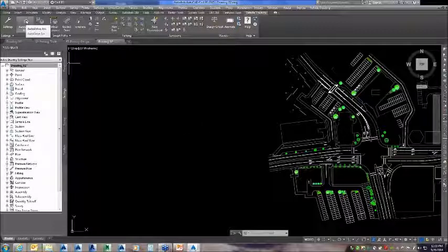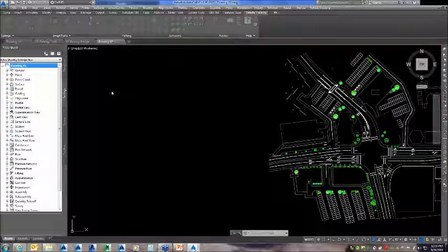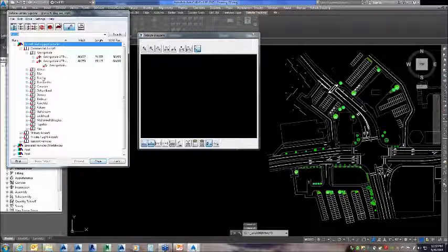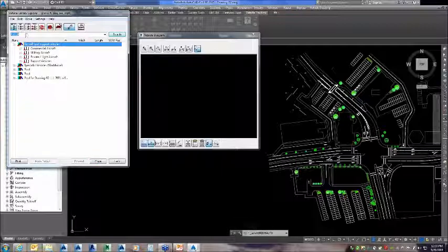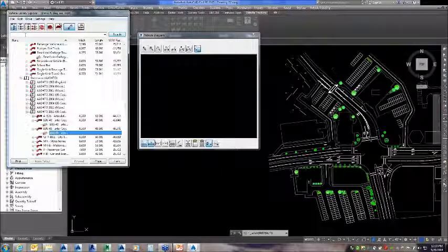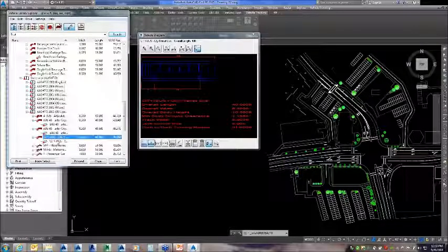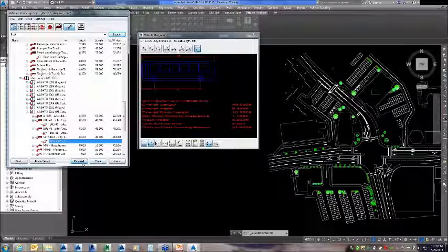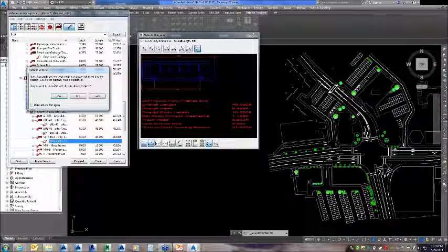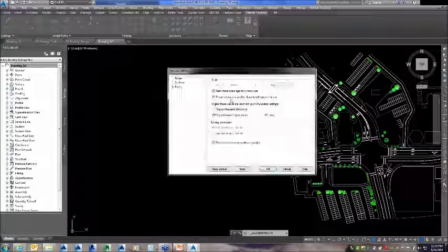So if I pick AutoDrive, just right here, it's going to bring up this dialog box again, and I'm just going to go down and pick a specific vehicle. So if I go to search, I'm going to go down and just pick a specific passenger bus. And I'm going to select proceed, and it's going to ask me if I want it to have a default. I don't want that to have a default. And then it says auto track and then specific path.